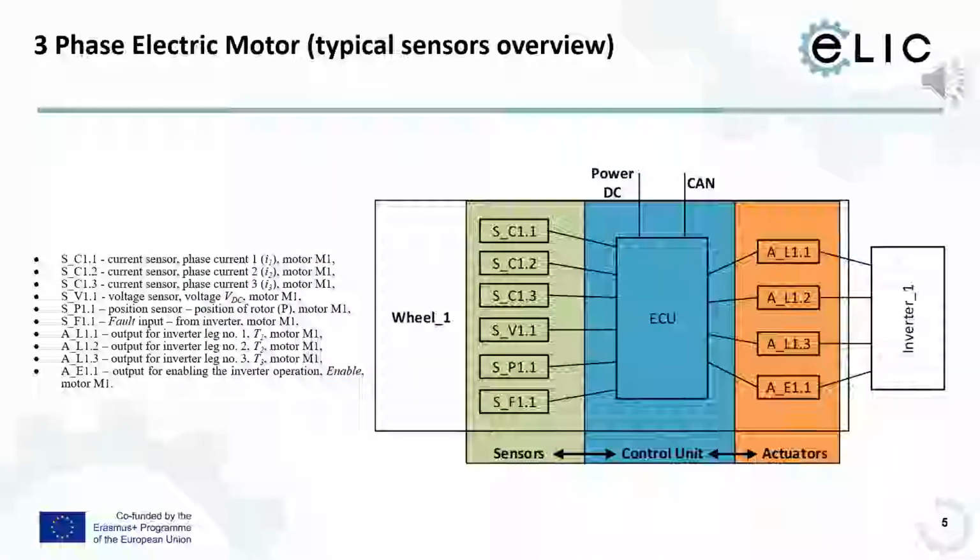This slide shows that when we want to control an e-motor, we have to measure back some of the values of how we control the e-motor. For instance, we provide currents I1, I2 and I3 on the 3 legs of the motor. In this case, the legs are the coils we have mentioned before in the previous slide. And we would like to measure back, of course, if these currents are operating correctly.